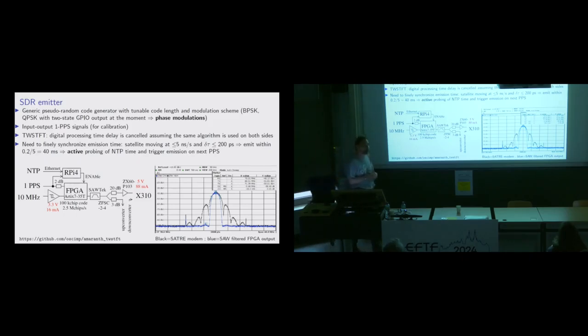As I discussed yesterday, the fewer analog components, the better we live, because the fewer drifts, the fewer things to characterize. So basically, the transmitter is just an FPGA. The 70 megahertz carrier is generated, the BPSK modulation, and the pseudo-random sequence are all generated in the FPGA. Originally, we wanted to have a compact embedded system using the same FPGA as the receiver SDR. This is still an option, but if you're developing an FPGA, you know that synthesizing the X310 gateware is something like a 3-hour synthesis, and when you're developing, it's super annoying.